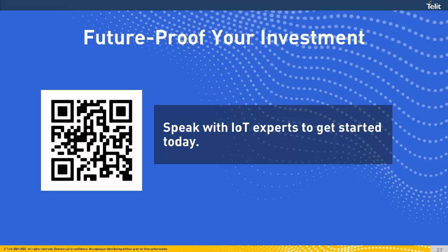But these two modules also have a coexistence port that gives the possibility to the two modules to communicate and coordinate. So in this case, if the LTE module is transmitting, it can send a message to the Wi-Fi module to say, please wait and resume as soon as I finish. And vice versa, if the Wi-Fi module is transmitting, you can set the priority and decide if the cellular modem has to take priority and start transmitting, stopping the Wi-Fi, or just let the Wi-Fi module finish. This is something that can be easily programmed.